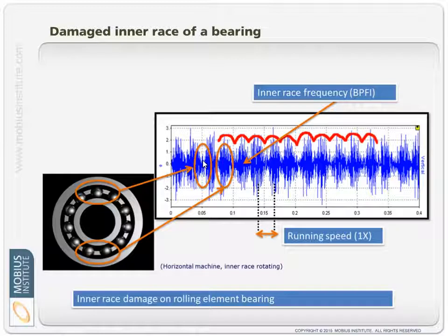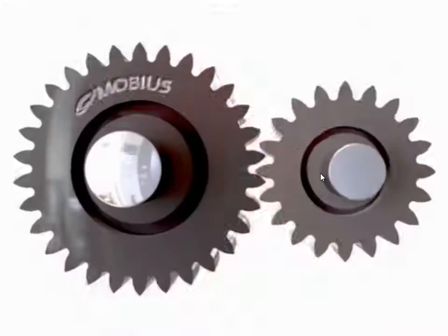This time waveform tells me about the nature of the fault condition and tells me about the severity. How many G's of vibration tell me how severe the problem is, and it's something that I can monitor over time. So that's a very useful sort of display.